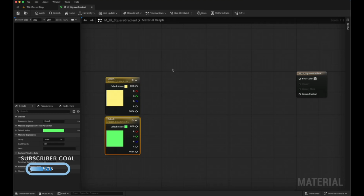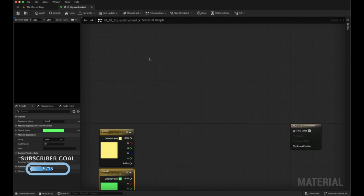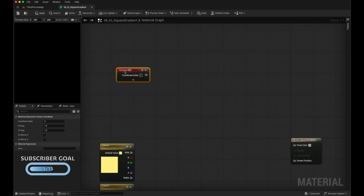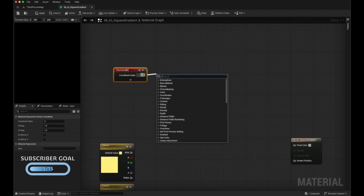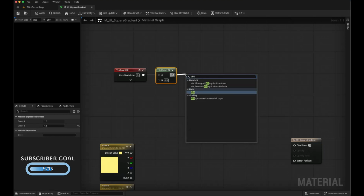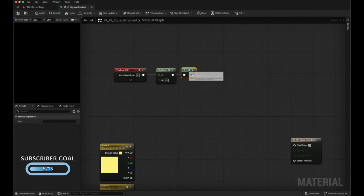Cool. Now we will use the text coord node to build our UV map. Let's find some empty space and search for text coord. Now remember, text coord gives both our UV values in the form of a vector. So when we use the subtract node, both our U and V values get affected. So we are subtracting 0.5 and the center is now at 0, 0. Next we will use the abs node to get the absolute values. Perfect. Now all our negative values are gone.